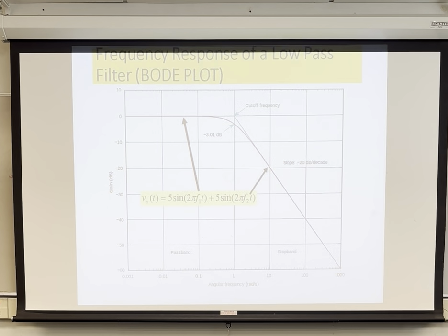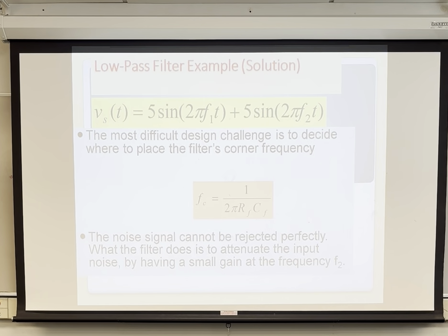So to do that, again, here's a version of the Bode plot similar to the PSpice one. We want to put the 100 hertz anywhere in this region where there's about 0 dB gain, and then once we pass through the cutoff frequency at minus 3 dB, the 30 kilohertz will be out here somewhere. Maybe minus 20, minus 30, or minus 40 dB gain. So it will be greatly reduced when it gets to the 30 kilohertz frequency.